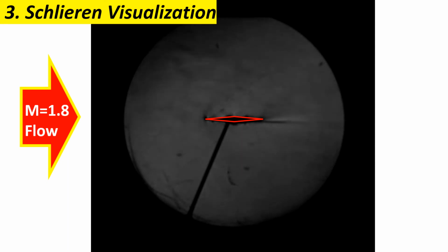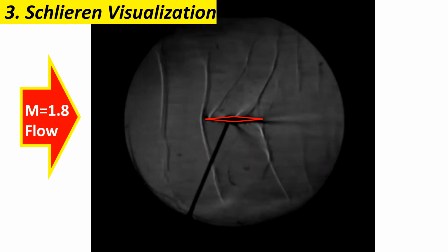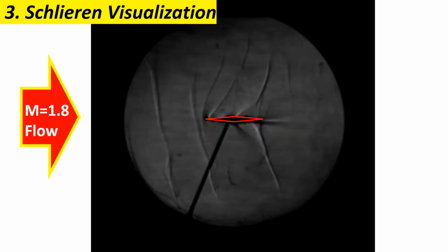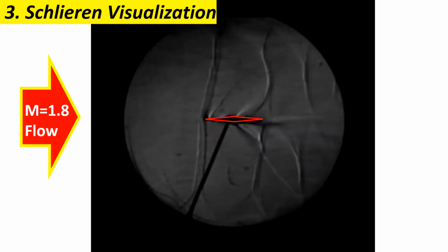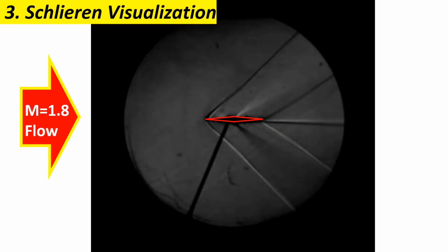accelerates. We can see the disturbance on the aerofoil already. So quickly it will become supersonic, and you will see the shockwave. Now it's transonic. You can see the shockwave is on the aerofoil, and also you can see the streaks in the free stream, and the shockwave becomes stronger. This is typical transonic flow. And okay, now we have the normal shock. It's about to fully start up, and the normal shockwave becomes attached.